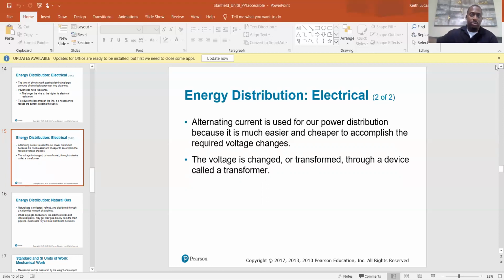So you have 120 volts coming in through the wall outlet that the furnace is plugged into, and that 120 is operating all your motors and stuff. But then that same 120 is going into your transformer, and because it's a step down transformer, it's coming out at 24 volts. And that 24 volts is what operates all your controls, opens and closes all your switches, tells things to come on, and sends signals to and from the thermostat and also to the contactor outside.